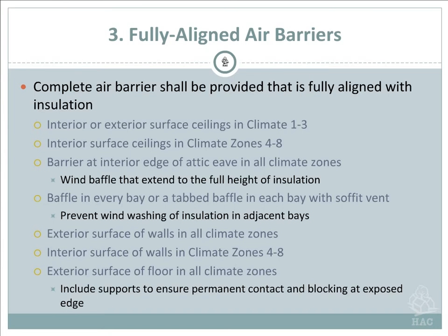Again, all the exterior surfaces of the walls have to be insulated. We'll talk about the different insulations that you need to put on exterior walls. Again, depending on what climate zone you're in, that's the insulation or the R values you need to meet on the inside and also on the outside. Again, take into consideration, there are various techniques of doing other things besides this. You could go with an R13 inside, a blue board on the outside, and then you wrap it, and you get an R23 on that wall, R24. So again, there are different ways of reaching that.